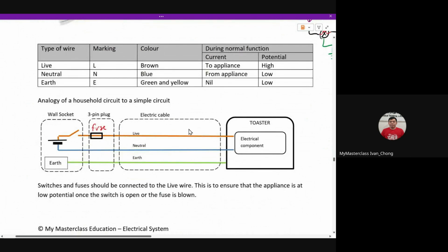So your live wire goes in. What happens? It goes in, it comes out. So basically, you can see it flows like that, right? Now, this is assuming everything is normal. However, if things are not normal, what happens is maybe there's a problem over here. Okay, which means you are now spoiled. Okay, the wires now touch the metal parts of my metal casing.